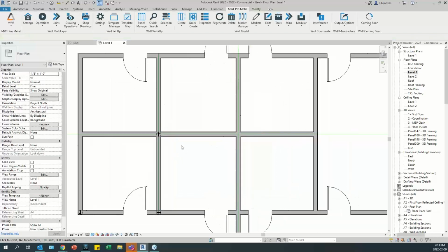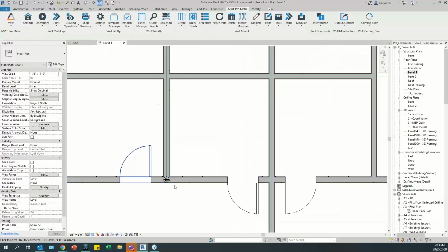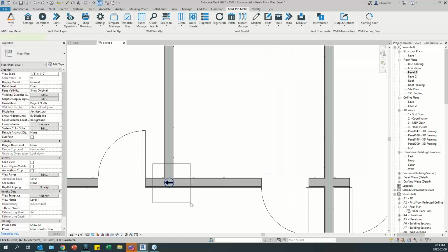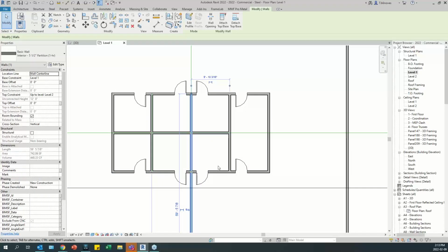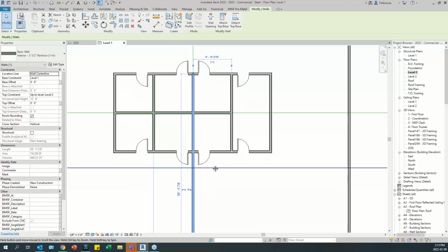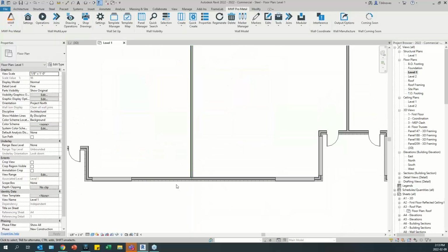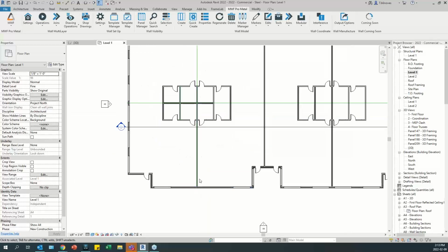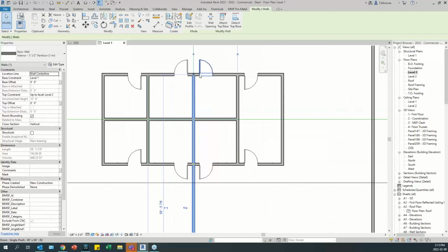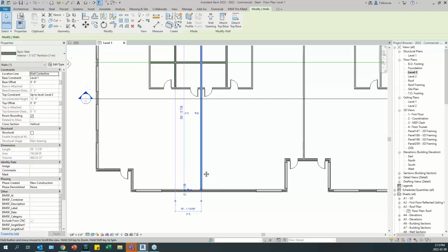Okay, so that would be one thing that we would need to do before going ahead and placing our joints. The other thing is also, for example, this wall here. You're going to see that also depending on how the project is modeled, if, for example, you go ahead and place joins in all of these walls, but you forget to place a join here, for example, some of the panels may not create, and that is because it's missing one corner condition here. You're going to have some of the joints here in relation with this wall, but here at the corner at the end of the wall, you're not going to get any joints, and that could cause some issues as well.